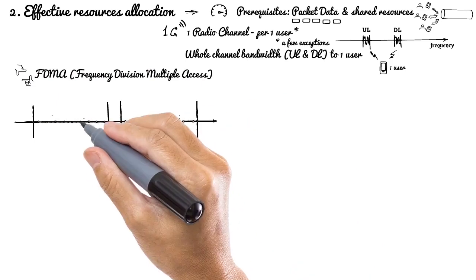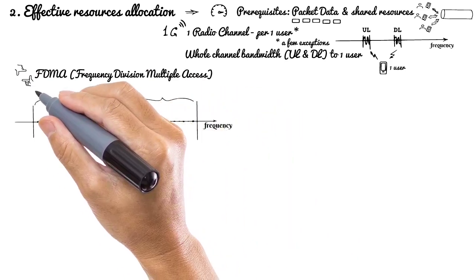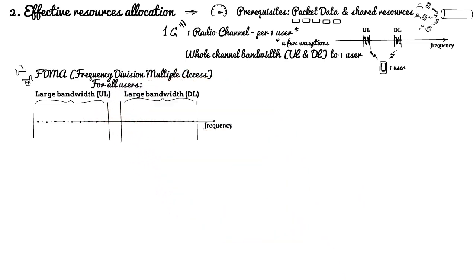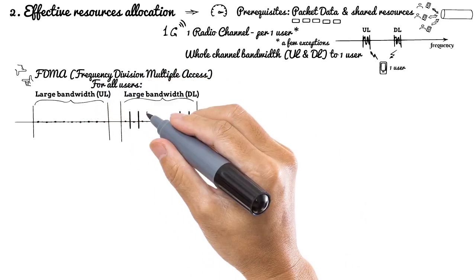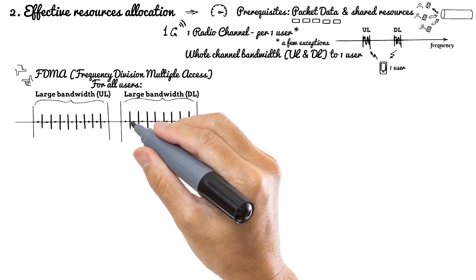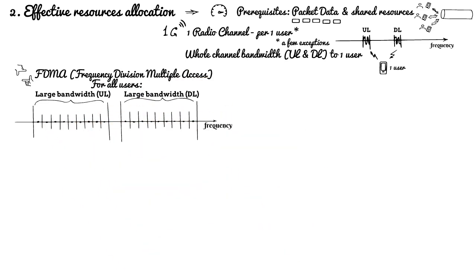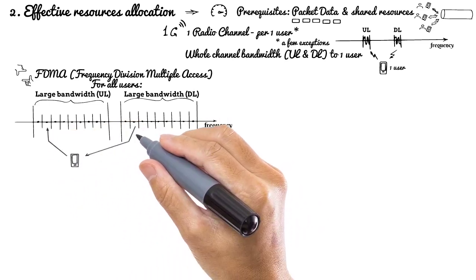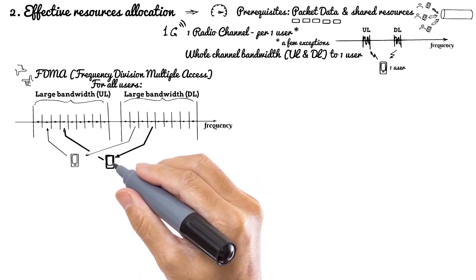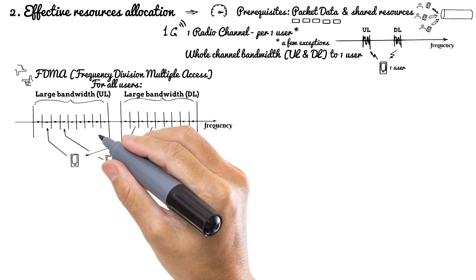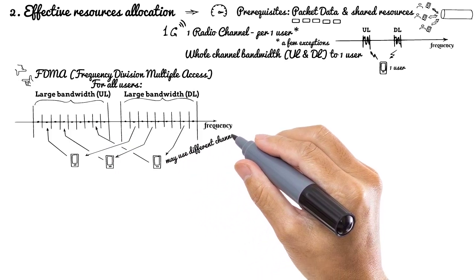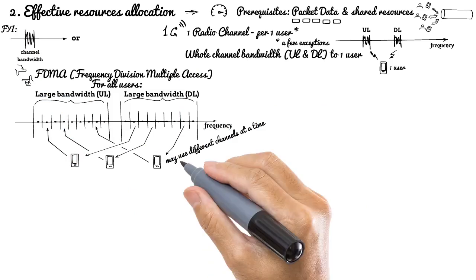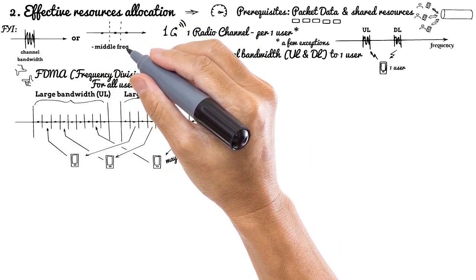Simplified idea of FDMA is that a large radio bandwidth is allocated for radio transmissions from all users. And this large resource is divided into a list of a limited number of narrow radio channels. Each of such channels has its main frequency in the middle of the imaginary bandwidth and can potentially be allocated to any user. So multiple users can jump to use network resources at the same time on different channels, each user on its channel.